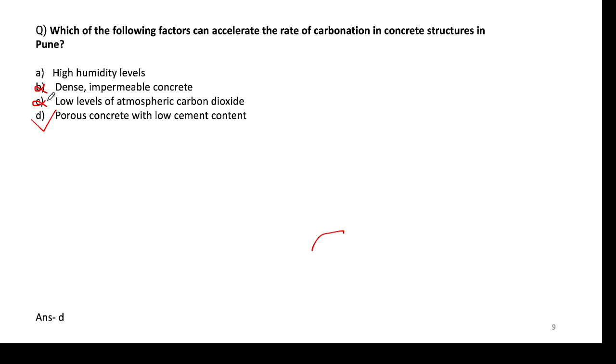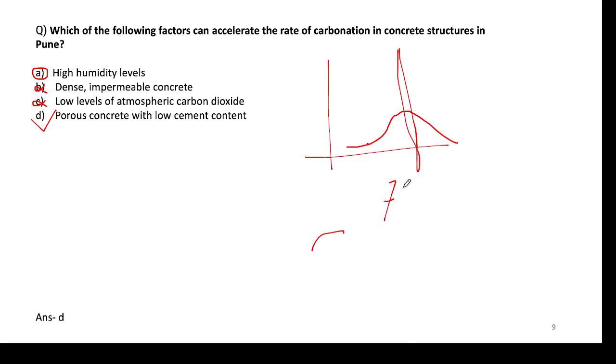Higher relative humidity will not be the answer because it is observed that the carbonation rate follows a trend like this, where the higher carbonation rate is observed around 70 to 80 RH, and after that it is lower, and before that it is also lower.